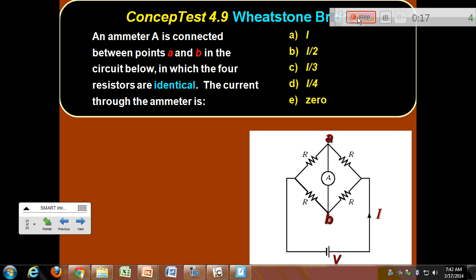Makes horrible bread. Wheatstone. Right. It's used to measure unknown resistances. Don't really use Wheatstone bridges anymore, but people used to use them. If I have all 4 resistors here identical, what is the current there through that branch, through the ammeter? What is the current?